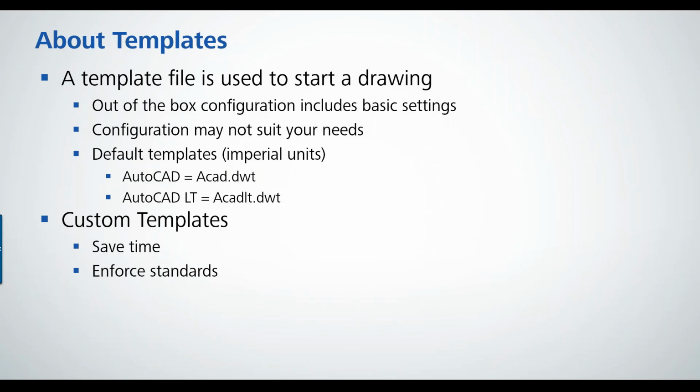So why create custom templates? Well, it will save you time in the sense that when you start a new drawing, you don't have to add your layers or add your plotter settings to the drawing. You don't have to recreate all this stuff, layouts, text styles. The stuff is there when you start a new drawing. All you have to do is create your work, and the rest is already done for you.